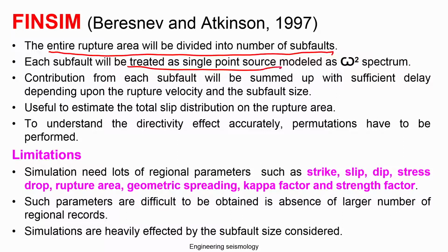So, here instead of one single point simulation by Boore, these people divide the rupture area like this, and then model each segment as a point source with an omega square spectrum. The contribution from each subfault will be summed up and suitably delayed depending upon the rupture velocity and subfault size. Then finally, they arrive at the total ground motion from these small subfaults.